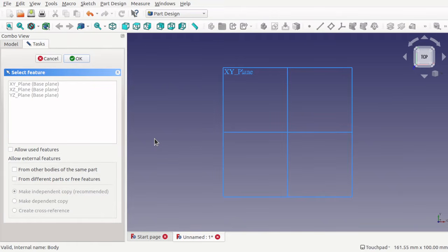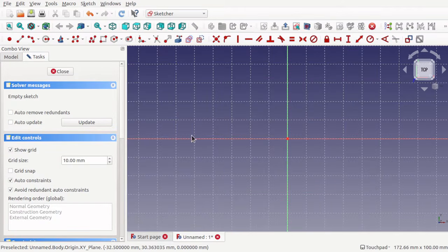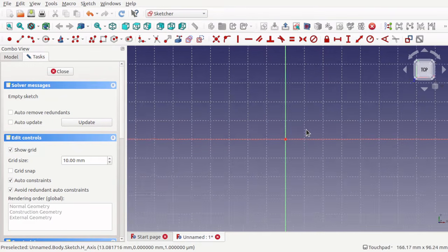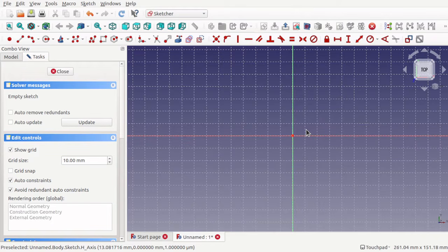This is the reason why you need datum planes, because you're going to place a datum plane on one of those profiles, because we can only do XY, XZ and YZ for our sketching, but we need another plane probably along the ZX for the front of the shovel. So I'm going to start on the XY, and we're going to be looking down the shovel, and we're going to be using the vertical and the horizontal guidelines here, and we're building the model around the center.